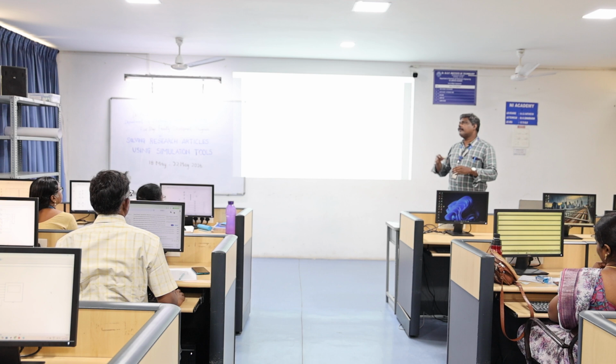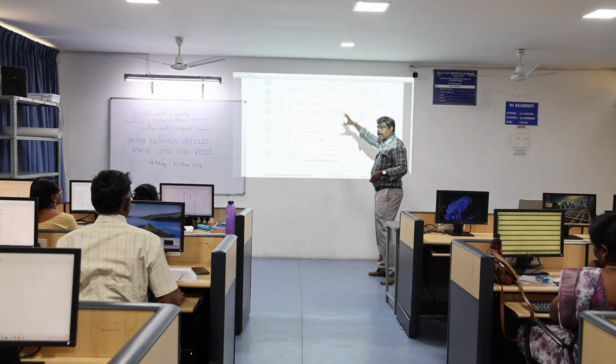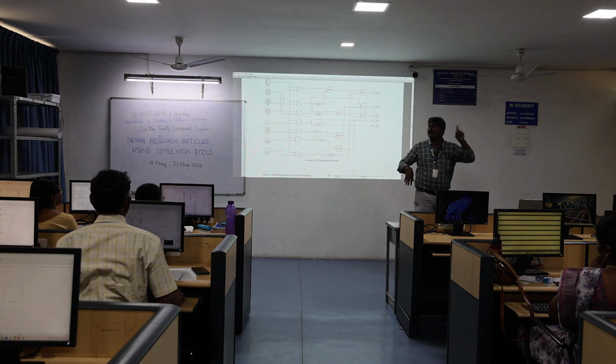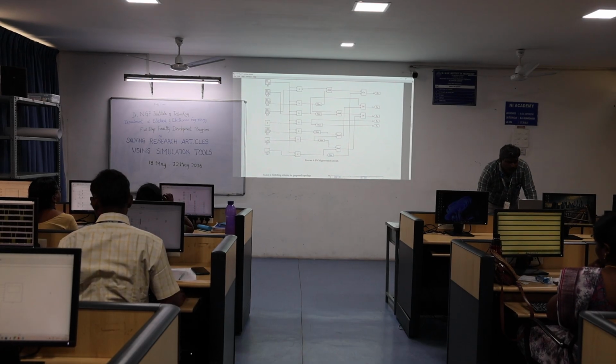You can apply either SOP (sum of products) or product of sums concept, based on that you reduce the logical expression. Based on our switching pattern table, we are going to form this logical arrangement using the K-map concept.